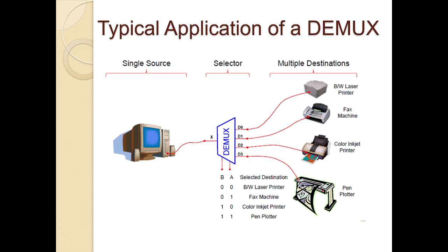In the multiplexer, one input is selected and reflected in the output. The demultiplexer is opposite to the multiplexer: the one input is reflected in different outputs based on the selection lines. That's why the demultiplexer is called a data distributor, and the multiplexer is called a data selector.